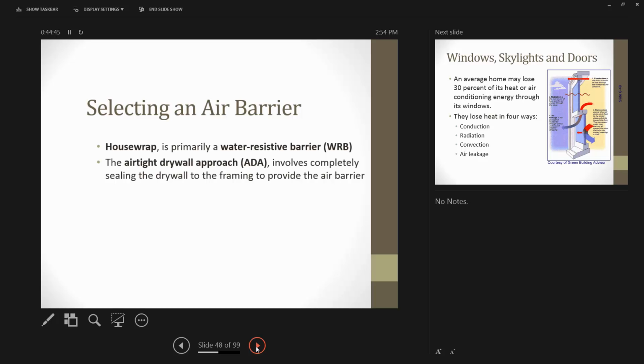But more and more we're looking at in building science getting to dryability, and that's what we'll talk about, the WUFI profile as the last thing we're going to talk about. And what that does is it evaluates your entire building assembly. It does evaluate where the thermal control is and where the vapor drive is, but it evaluates the ability of that wall to dry.